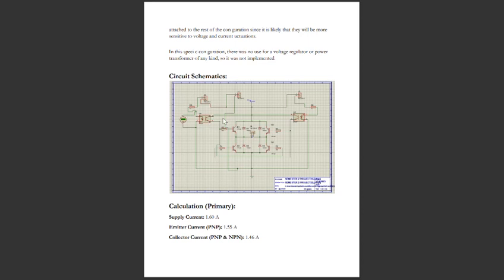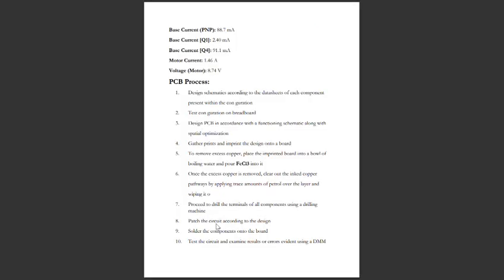This circuit is connected by this first optocoupler, and this optocoupler is connected. If current flows through this, then Q1 and Q4 are on. If current flows through this circuit, then Q2 and Q3 are on. In this way, it works. The calculations, we do some calculations on this.